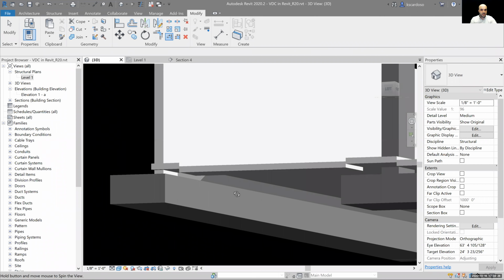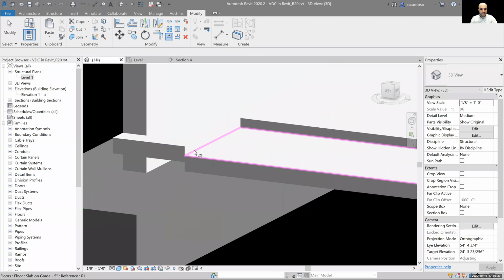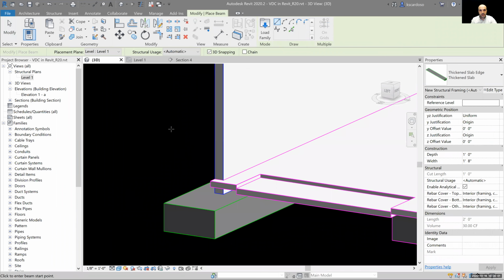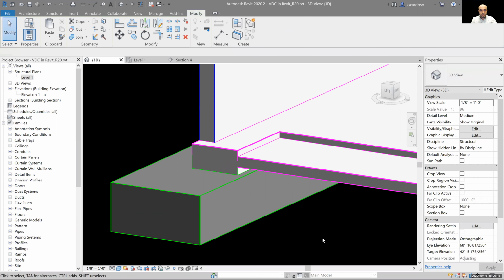And you can refine and keep adding more thickenings in here until that looks the way you need it to look. So for example, if I want to fill this part in a little bit more, I can add a thickening and select this vertical line, that inside edge of the step, because I know how the family works. It's going to start there and go in towards the wall, or I can add one here. So let's try that one. Let me grab that thickening, okay? And let me do a create similar, CS. You can see my cursor change, right? Now I'll hit pick lines there. Now let's select, we know that our depth is correct, right? Because it's at 1 foot. Let me select this edge. Okay, so far so good.